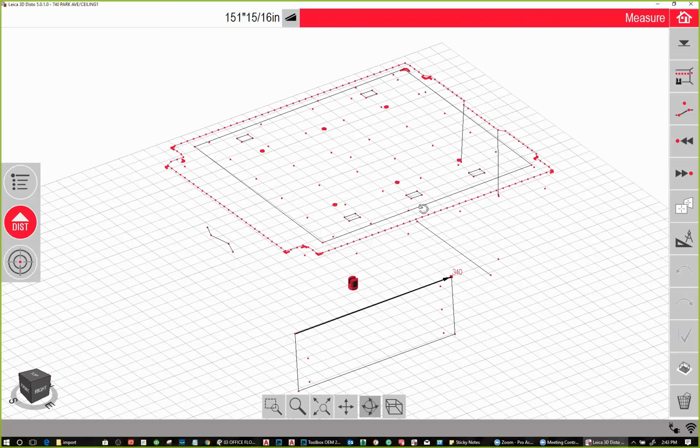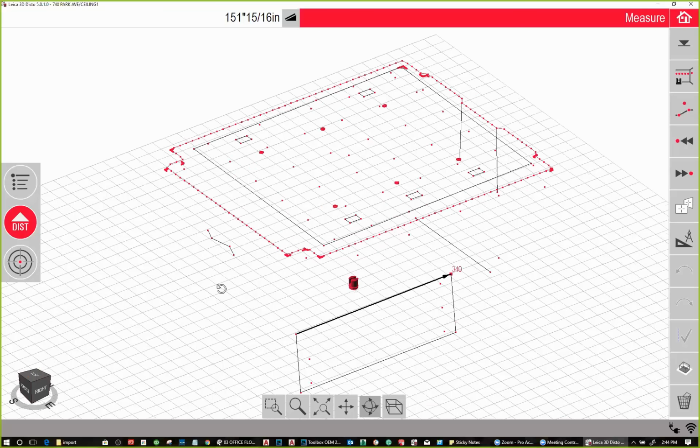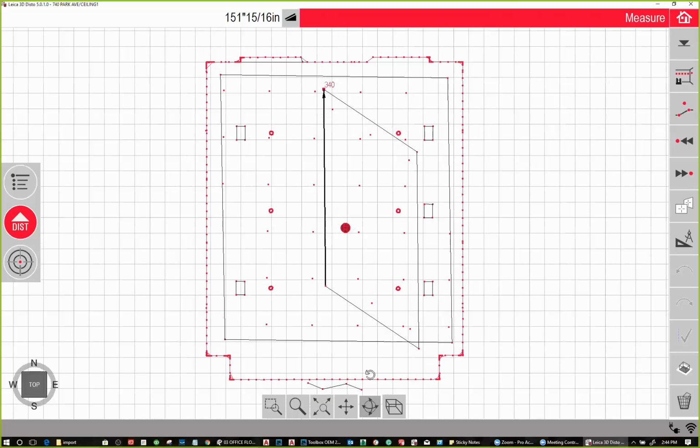What I would do is flatten this drawing in AutoCAD, and then I would add the points and the lines that I wanted to create those additional speaker locations, and then I would save that file with a different name and put that in the import folder. Then I would go back to the site and pick points of reference, like some points on the sides, so that I could orient this view so that the projection would be overlaid in the room properly.